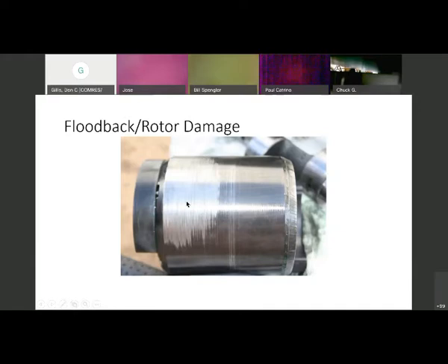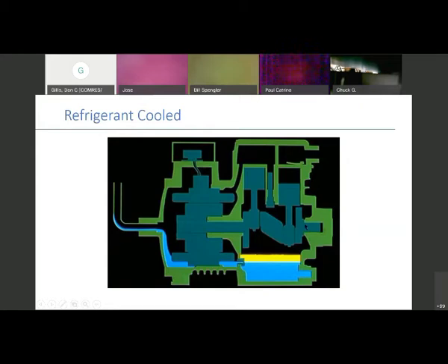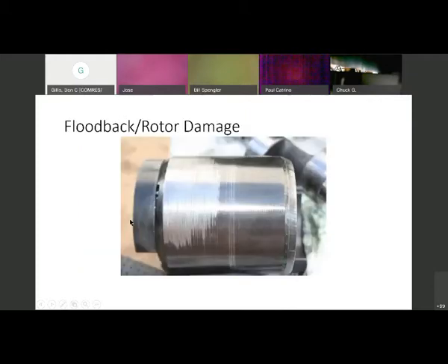See the scarring on the rotor here? I want to back up a little bit just for a second. So this bearing, this is all wearing down, and these bearings are becoming loose. I'm going to use the term sloppy, if you will. The weight of this motor starts to hang down as it continuously runs on. You've seen the wearing here. You've seen the bearing here. It's going to start to wear down and get some slop in there. It's going to start to sag from the weight of that rotor on there.